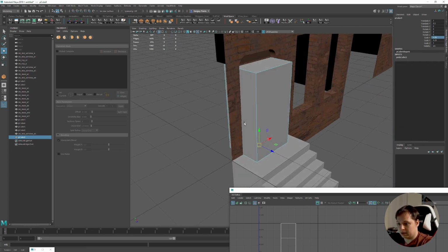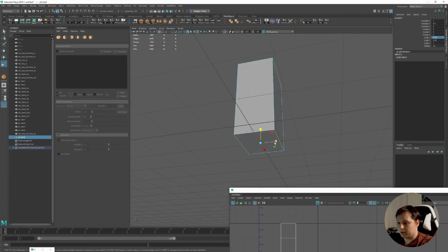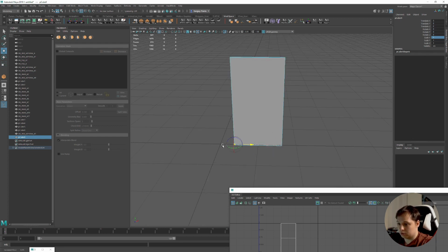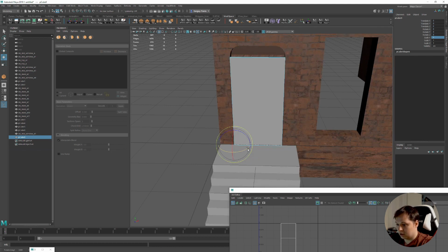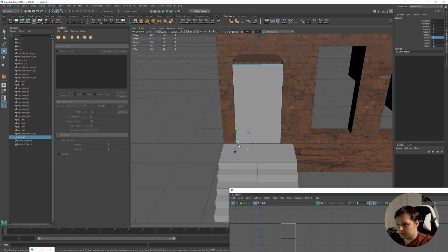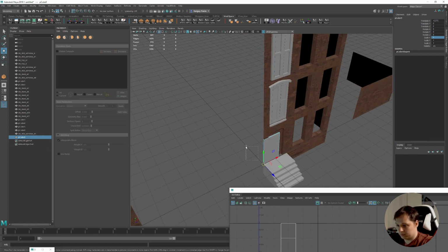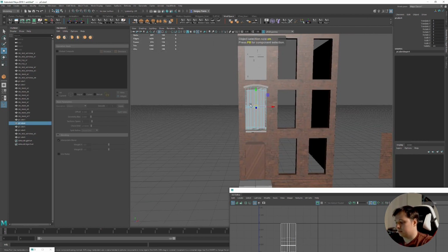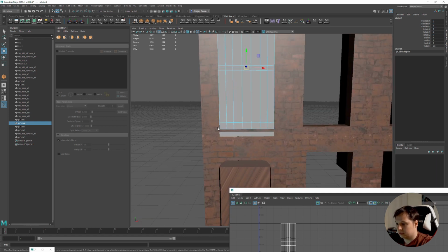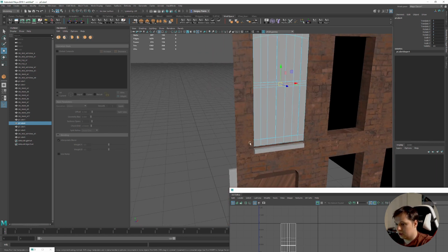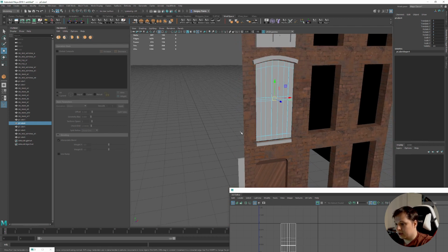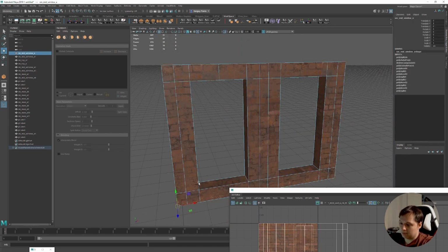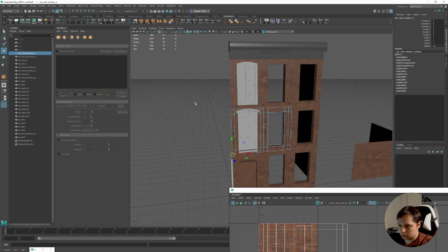It can be reasonable to place the pivot in the middle, but in a lot of cases you do not want to place the pivot of the window in the middle. You want to place it in the corner because you will be rotating it. If the pivot is in the middle for the door, it can be very problematic. So usually my pivot for the doors will be in the corner, and the pivot for the windows will be either middle or bottom, because in a lot of cases it's just more comfortable. It's not very comfortable when the pivot of the window is in the corner somewhere. Yes, it makes sense sometimes to make the same pivot for the wall because it will be easier to move.